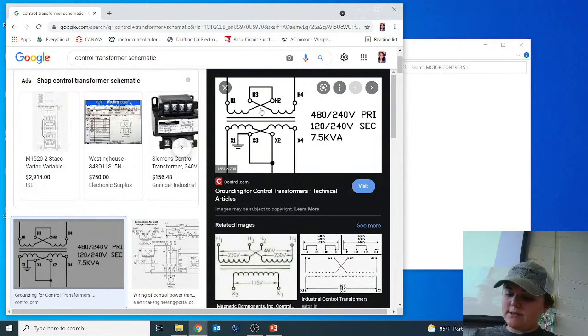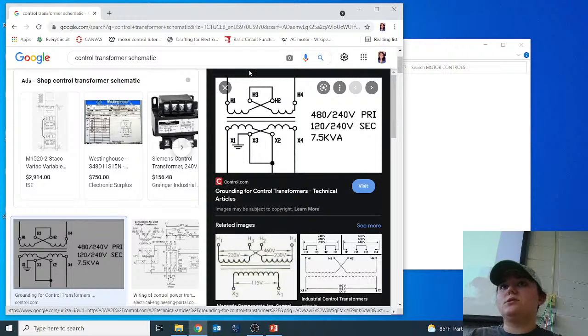So, anyways. Alright, so a control transformer is a transformer that is used to step down the voltage to the control circuit of a system or machine. The most common control transformers have two primary coils and one secondary coil. The primary coils of a control transformer are crossed, like how you see in here. They're crossed because normally it just looks like waves, right? There's nothing going on right here. It's just a bigger coil to a smaller coil if it's a step down, or a smaller coil to a bigger coil for a step up, right?